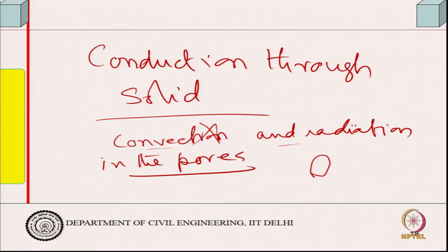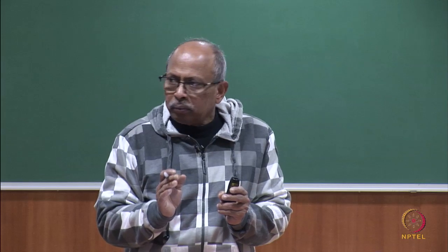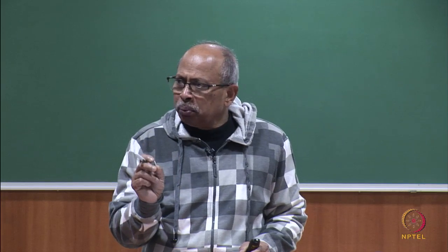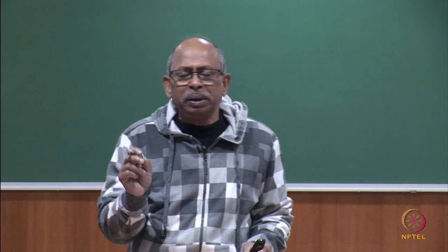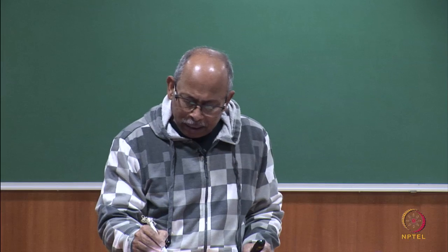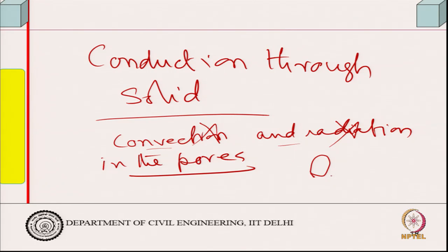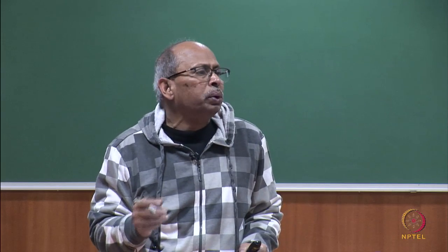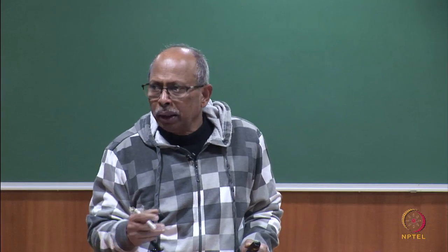This is a function of the temperature difference between hot and cold surface. In a small sized pore, this temperature difference is very small, and even so, for pores less than 0.3 millimeter, you do not get that. 0.3 millimeter means 300 microns. So, if the pore size is less than that, you are unlikely to get anything, and you will not get much of it in a closed pore system, convection or transportation.